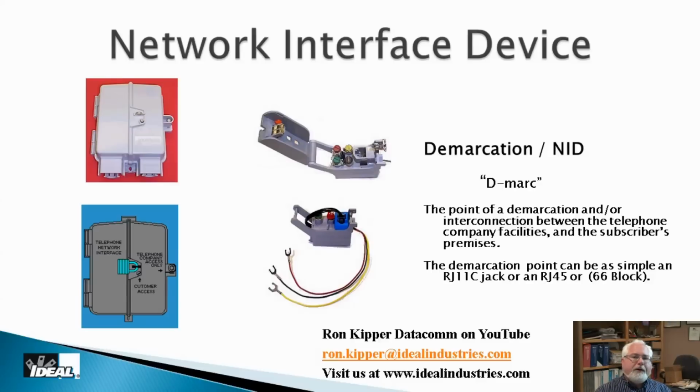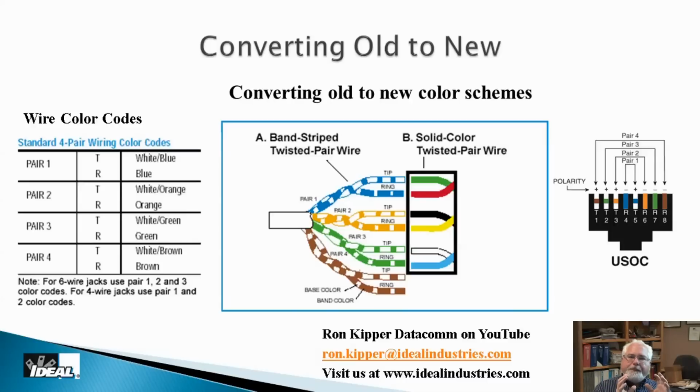So again, we're going to find a place from that box to mount our low voltage panel, and bring cable in. Now, the cabling we're going to use is considerably different from the old telephone wire. This old telephone-looking stuff, what we call quad wire, if you don't know, this stuff is not allowed to be used inside of walls anymore. You can only use it outside of walls. It's not fire rated to go in the wall anymore.